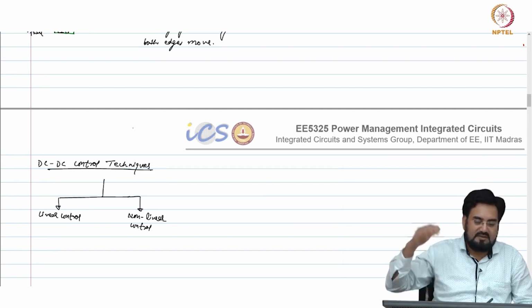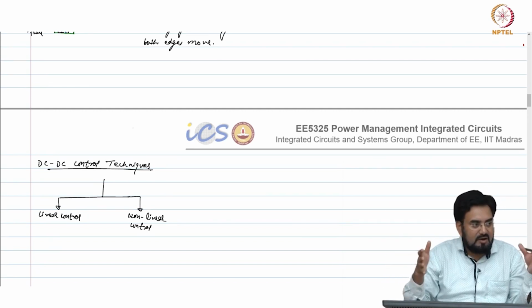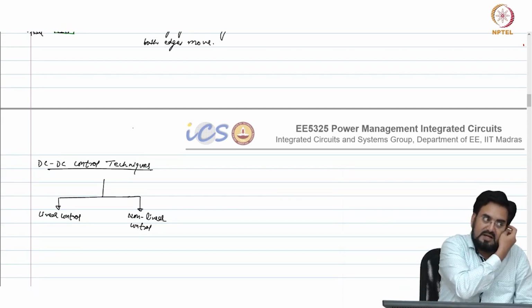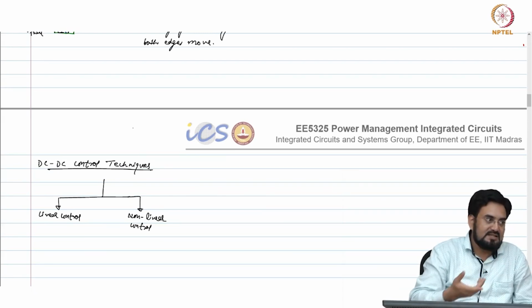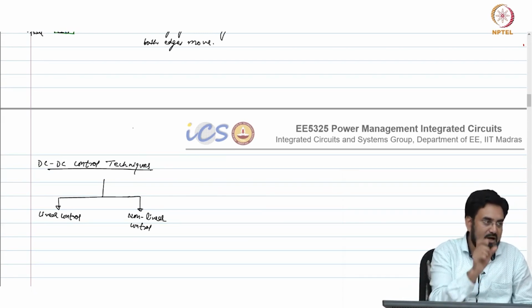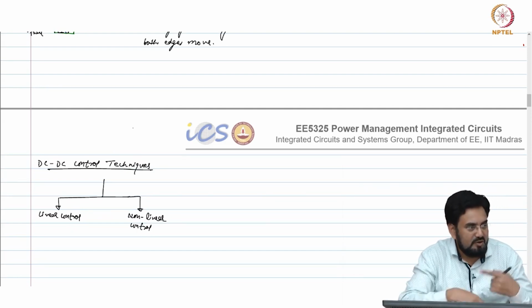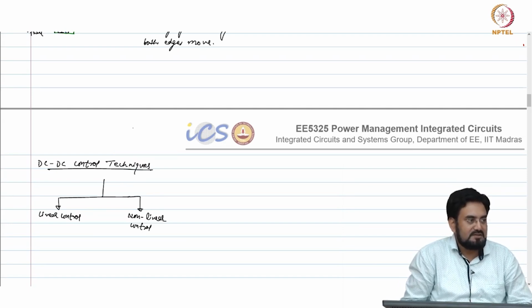But the problem is when your load changes, your IR drop in the power stage changes, because that is not ideal, that is lossy. Your power FET will have some RDS on, your inductor will have some resistance. So, IR drop will change. So, duty cycle has to change, and we already looked at how much delta D will be required in order to compensate for those losses.